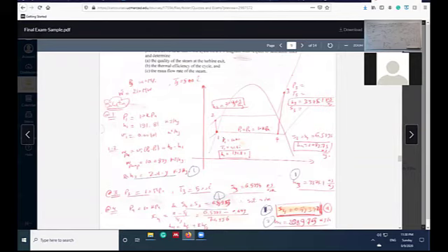Okay, let's go back to 2. 1 to 2. At 2, we have W pump equal VDP. Because you have the compression ratio, you have P2, which is P3, and you have P4, which is P1. You can get the work. And it is H2 minus H1. You have H1. Remember, you have H1. You have P1. You have P2. You have V1. You can easily get H2. And W pump if you want it as well, because we want it.